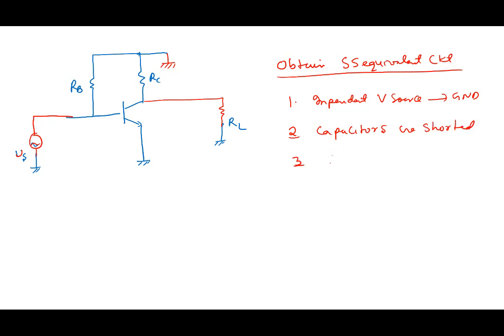If you want, simplify the circuit at this stage, because once you short and all that, you can simplify. So the simplification that we do is we remove, for example, here, we could just put RB here. Why put it there? Makes it easier. RB here, and all this we remove, and we can put here, we could see that it is RC parallel RL.